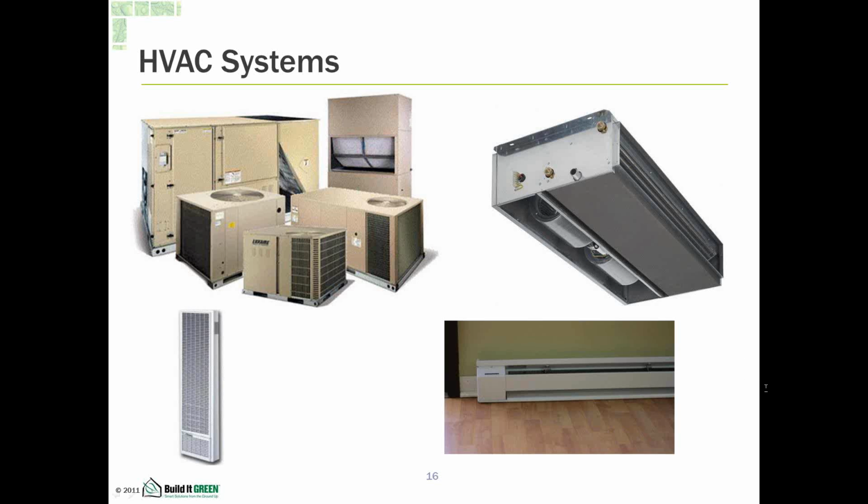So you would model the AirTap as an air source heat pump. I don't have the EnergyPro software on this laptop, but you would call it out as a heat pump and then put in the energy factor as 2.2. That makes sense, because it's a retrofit kit. So any more questions? Nope. Okay. So HVAC systems.